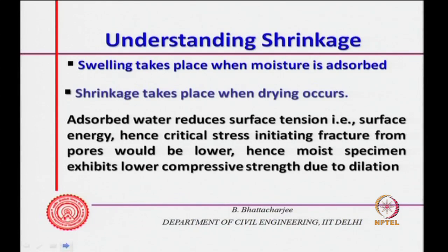So, adsorbed water reduces surface tension, surface energy, hence the critical stress initiating fracture from the pores will also be lower. Since the surface energy becomes low, if you recollect when we were talking of strength, critical stress is a function of E gamma, under root E gamma divided by pi into half of the crack width, or pi r. Now, surface energy is reducing when it is becoming moist, and therefore, critical stress reduces. Therefore, a moist specimen exhibits lower compressive strength due to this dilation effect.